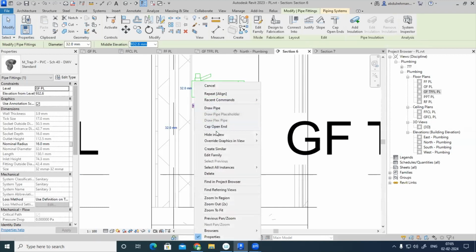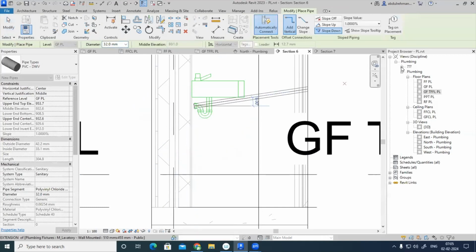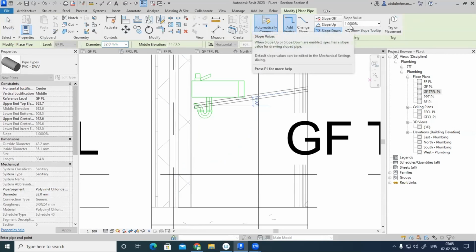So I'll be selecting here. Drop pipe. Since it is a horizontal pipe, we have to provide slope there. What slope? Pipe diameter less than 2.5 inch. This is like 1 into 1 by 4 inch only. Pipe diameter less than 2.5 inch. The slope should be 1 by 4 inch per foot minimum, or 1:50 slope, or 2% slope. So as per the standard, IPC I'm saying.